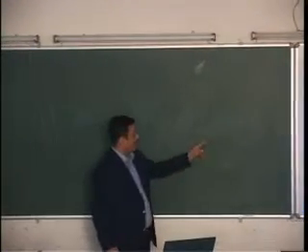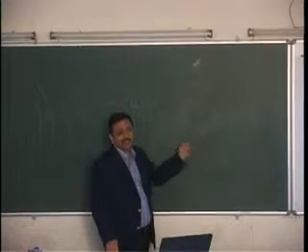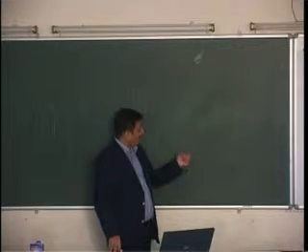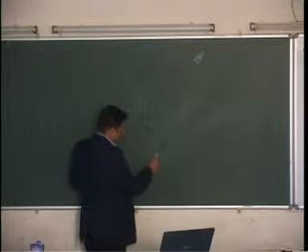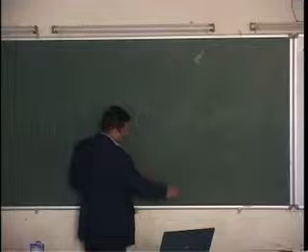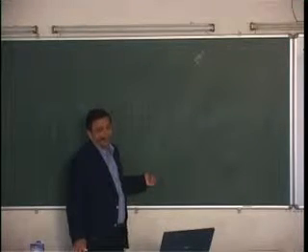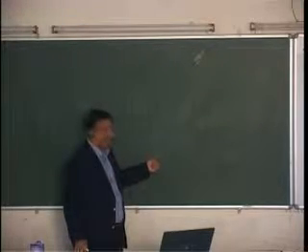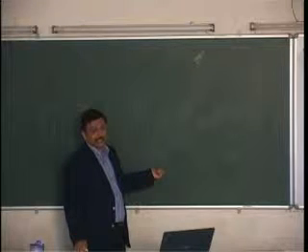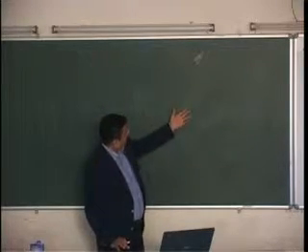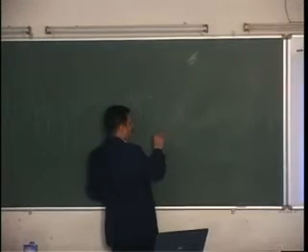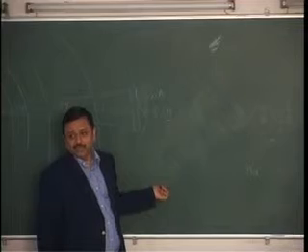are basically radiating microwave signals. Their noise is being picked up by the side lobes of the antenna. And if the back lobe is picking up the ground, the earth is also a major source of transmission in the microwave region. So the back lobe also picks up noise from the ground. So any antenna mounted on a spacecraft that is looking towards the ground, the main source is the ground itself.